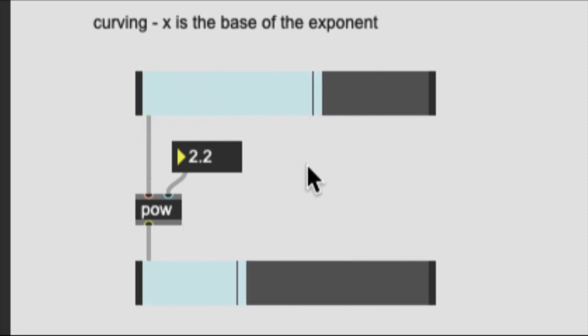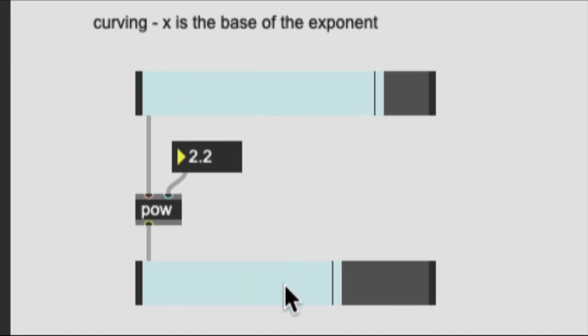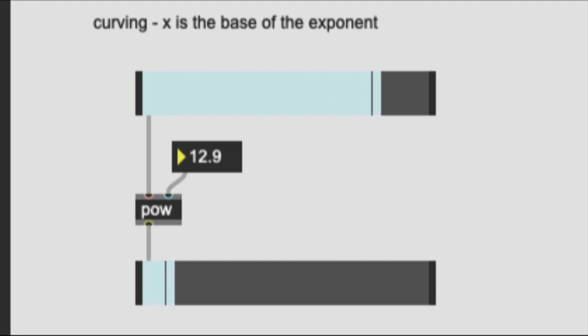Now remember, this works in the range 0 to 1. If you change the range here, it will be breaking it. So if you want to use this curvature, what I suggest is first make the curvature in the range 0 to 1, and then do another range conversion, a linear range conversion, if you need a different range there. So that's values larger than 1. I mean, obviously I can crank it up, and then see, it's completely glued to 0, and then only in the last bit it will suddenly jump up.